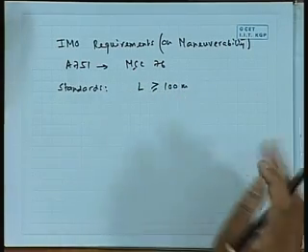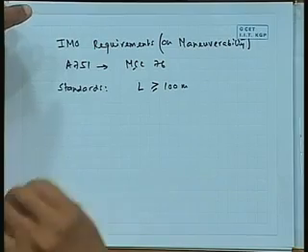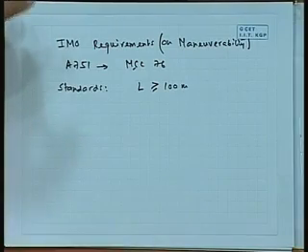Small ships normally, we should understand this. They are interested sometimes in the rules and regulations in the absolute dimension. You see, the port is 500 meter. Now, if the ship is small, say a 50 meter boat, even if it has 5 or 6 times its turning radius, it will still be 300 meter, less than 500 meter. But bigger ships will require more space. That is why the rules are more for bigger ships, 100 meter and above, mostly ocean going ships.